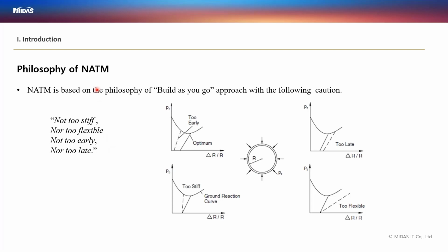Now, NATM is based on the philosophy of a build-as-you-go approach, with the following cautions: your support should not be too stiff, not too flexible, and the installation of the support should not be too early and not too late.